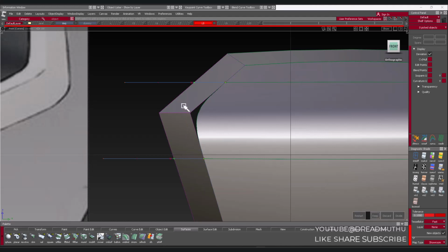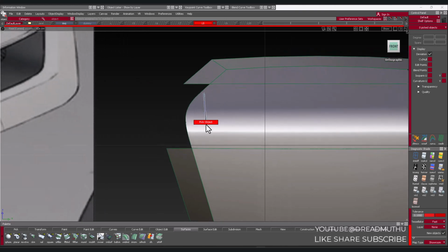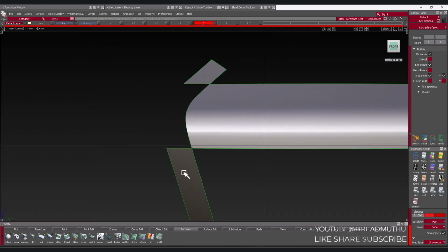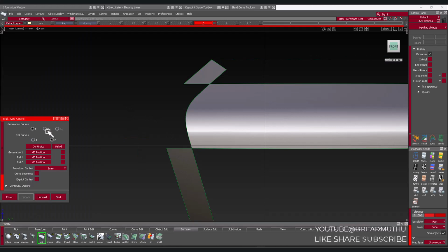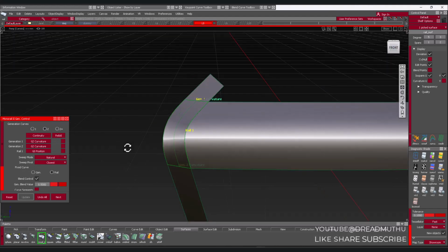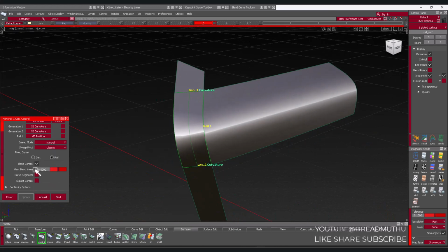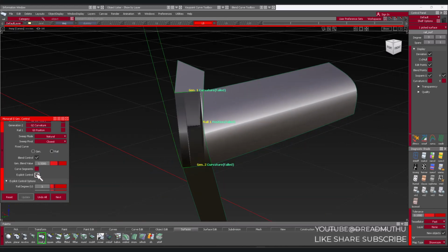Start. It's only these curves, so we'll use these 3 surfaces. We go for rail, G2, and in rail we need position. Yeah, okay, and select explicit, we'll make 5 and 5.